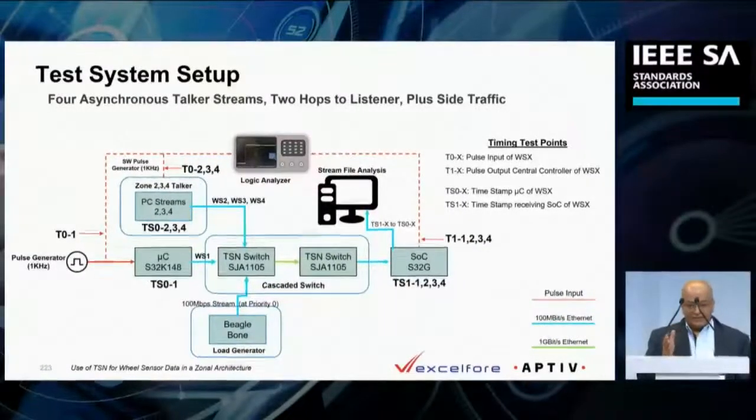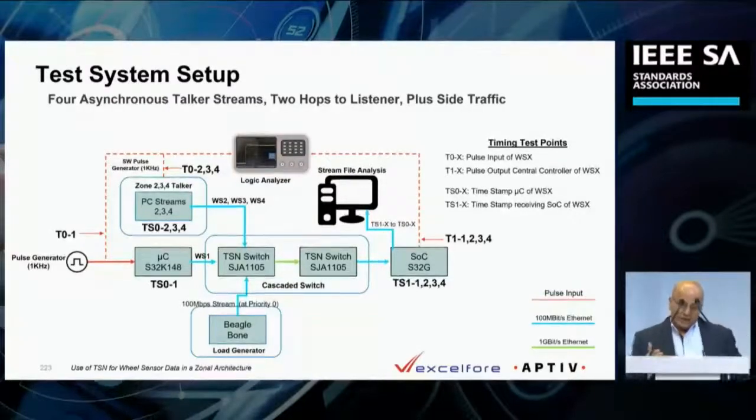The other challenge you have is that last year it was very hard to procure systems for anything. So we had to innovate as to how to get what we wanted and still be able to simulate and get the proper results. In this case, we got one real controller, which is the S32K that has the input in it for a real wheel sync in, and then used simulated pulses that reflect the wheel sync from a PC. Then they're all brought into the TSN switch at 100 megabits, including the injector.